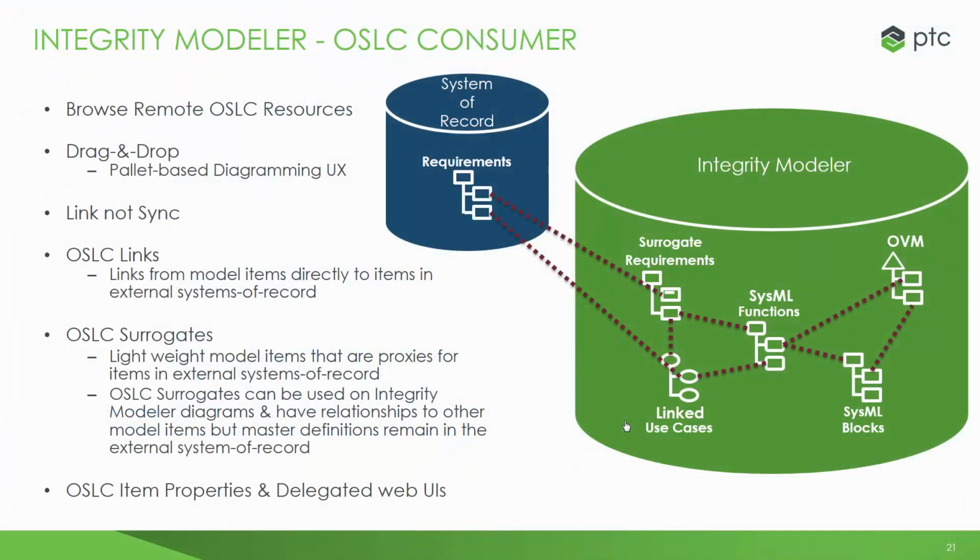So, as we've just seen, the Integrity Modeler OSLC consumer lets you browse remote OSLC resources from right inside the Integrity Modeler user interface. And then from that palette of OSLC resources, you can drag and drop them onto diagrams. This is then linking them and not copying or duplicating the data in the Integrity Modeler database.